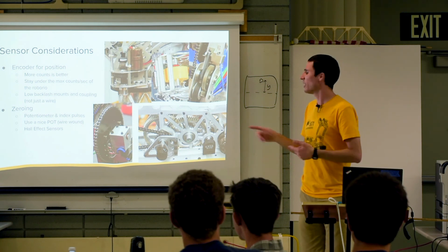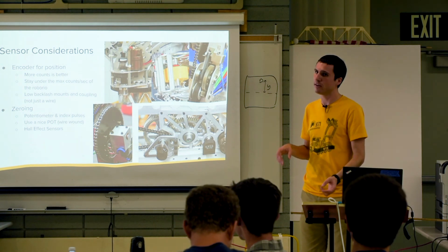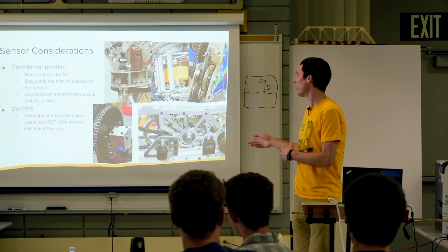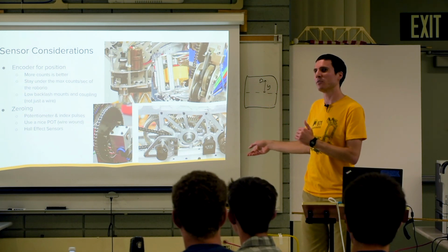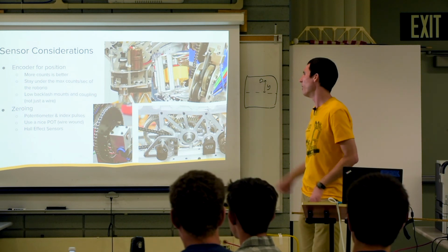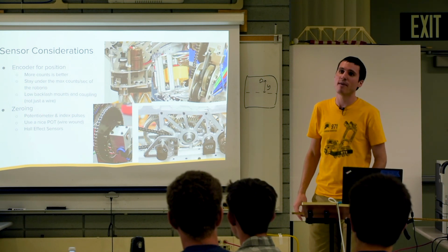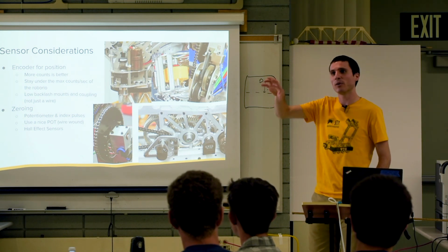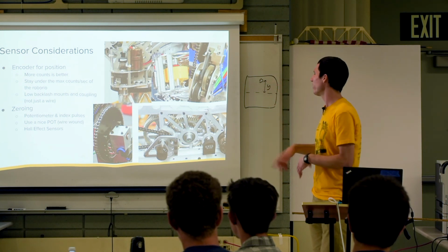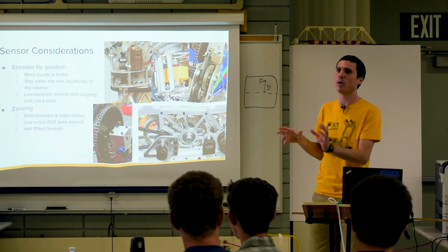The problem with a potentiometer is it's not enough resolution to control off of. If you look at it, the signal is very noisy. But you have the encoder. Encoder is good for relative position, potentiometer is good for absolute position. So you use the two together. Remember the magnet sensor you mentioned told you where you were within 1 revolution, right? So you can use that, or you can use an optical sensor that has what's called an index pulse, which tells you where you are in 1 revolution.